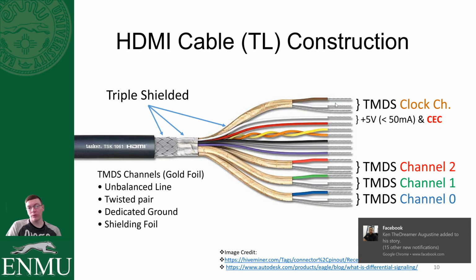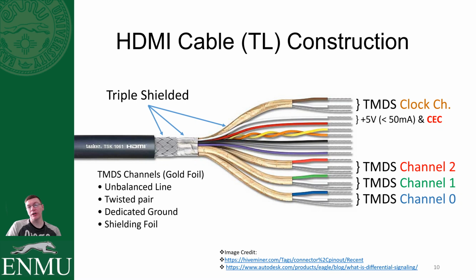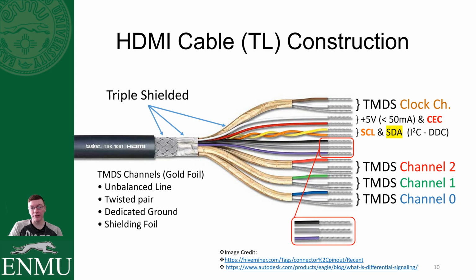And what happens with that is when you get that return detected, that means the cable's been plugged in, and it can begin exchanging the display identification data on the serial clock and serial data lanes, which is an I2C DDC channel. And then I'll bring those down here so we don't get too crowded there. That's your DDC, Ethernet, and CEC return ground. That's your hot plug detect. That was the one I was telling you about, that the 5 volts is returned on. And then, of course, that purple one might be the HDMI Ethernet channel.